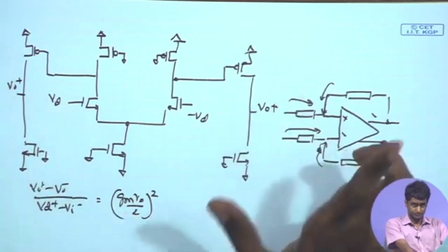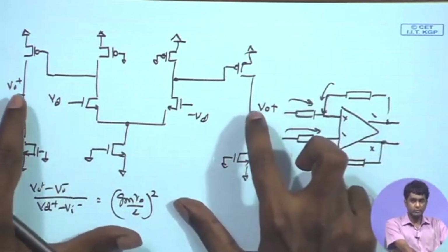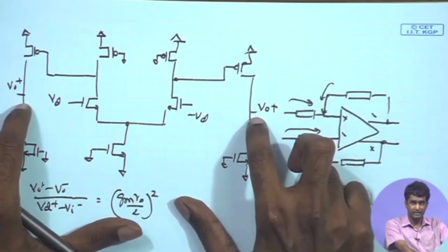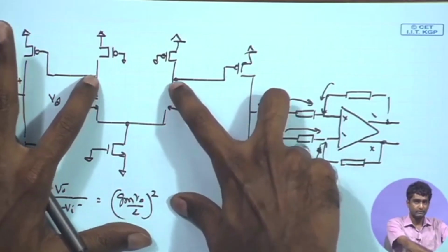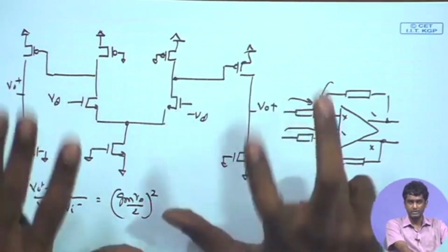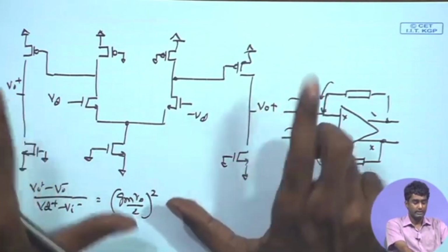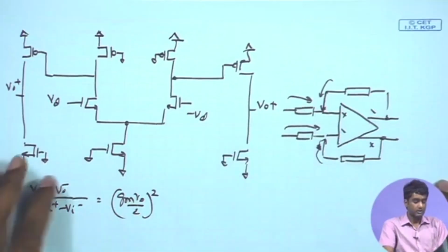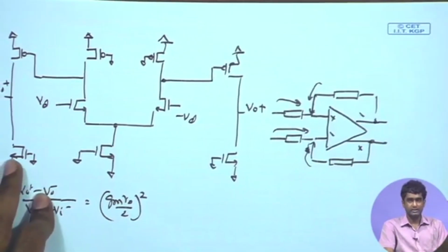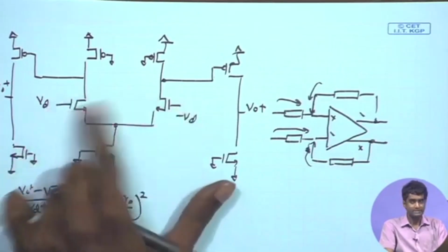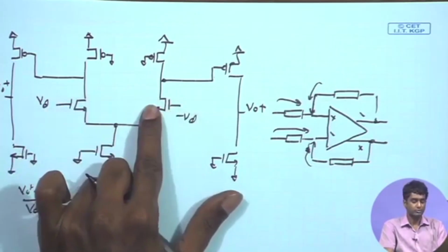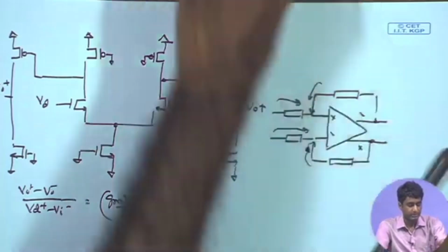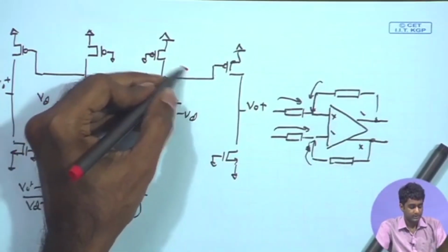So remember that using the common mode feedback, we are assuming that we have already set the output DC bias to an appropriate value, and also the DC bias at the output of the first stage has been set to a desired value. Now the next question is, how do we set the input DC bias? If we recall some of the very common steps that you might have taken in an undergrad lab to bias a differential amplifier or a common source amplifier, it is using a voltage divider. So for a differential amplifier, possibly we can think of using a voltage divider.